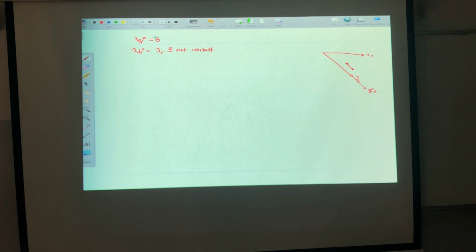Now let's return to the rotor voltage equation and discuss VDRE, which was equal to 0 by assumption, squirrel cage shorted. This was equal to RR IDRE plus d by dt of lambda DRE plus omega minus omega R lambda QRE. Now still lambda QRE is equal to zero. But this one's not equal to 0 anymore. Why? Because I'm allowing lambda DR to vary. So now IDR is not equal to 0. Simply now, 0 will equal RR IDRE plus d by dt of lambda DRE.